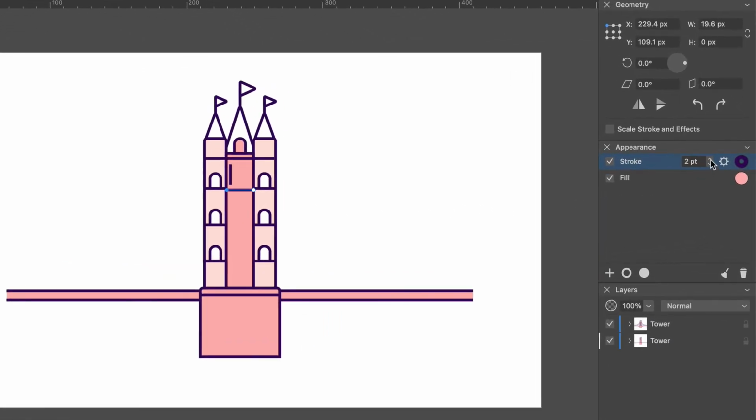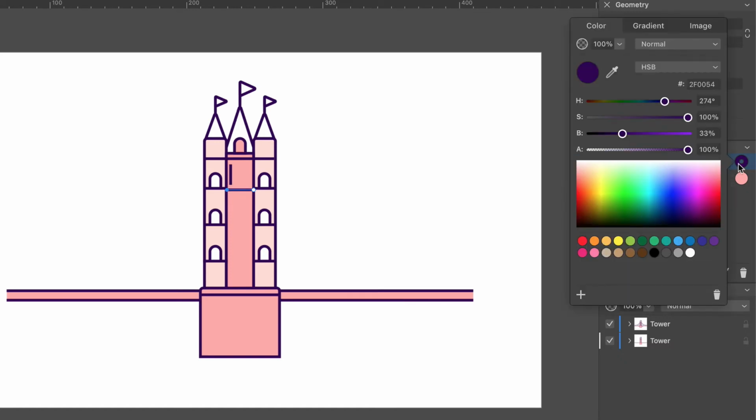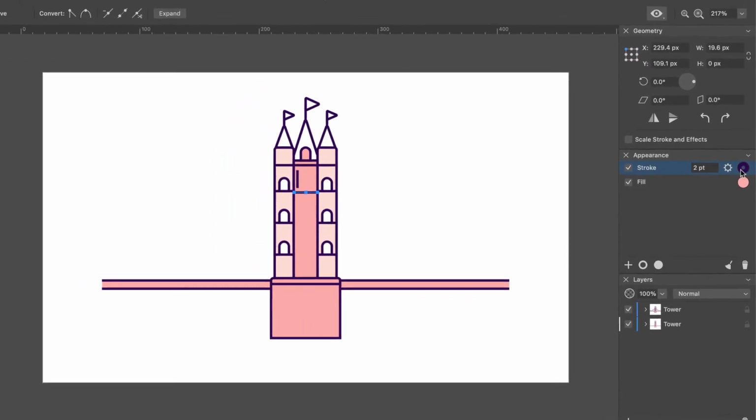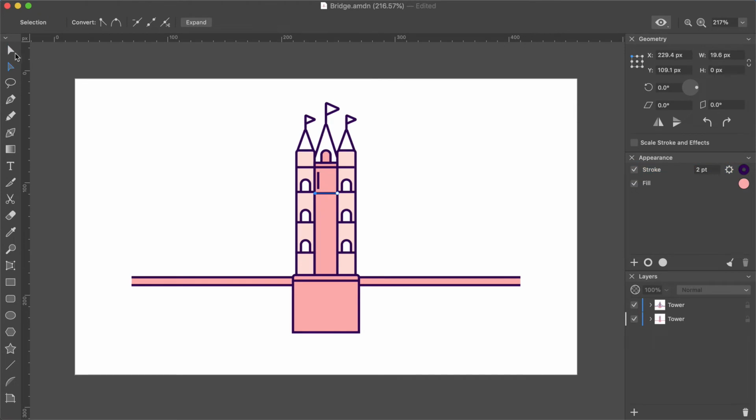If you want to change the width of the line, use the Stroke settings in the Appearance panel. Here you may also change the color of any line. We will explain the specifics of this panel in one of the following lessons. Now let's switch to the Move tool to adjust the position, color, and width of all straight lines that we added